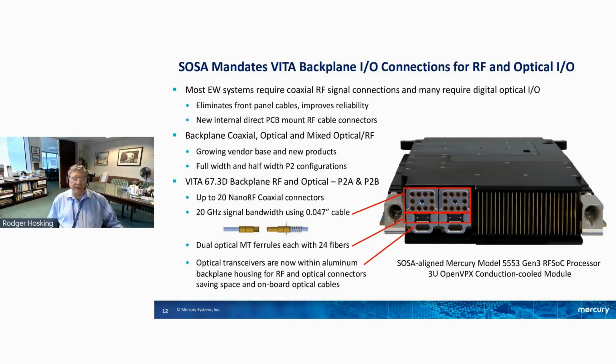Now, the rear panel I/O is mandated by SOSA for all of the analog inputs and optical inputs and outputs. And so there are new connectors that have been devised, new housings that have all been incorporated within VITA standards to support, in this example, up to 20 RF coaxial connections on the backplane and 2 optical MT ferrules, each with 24 fibers in. This gives you a lot of very high density, high performance, high bandwidth I/O across the backplane to comply with the new SOSA requirements.